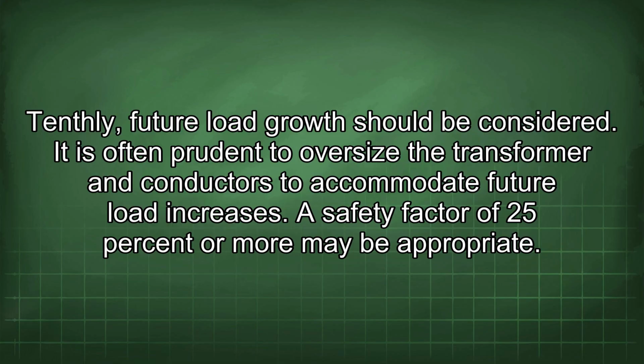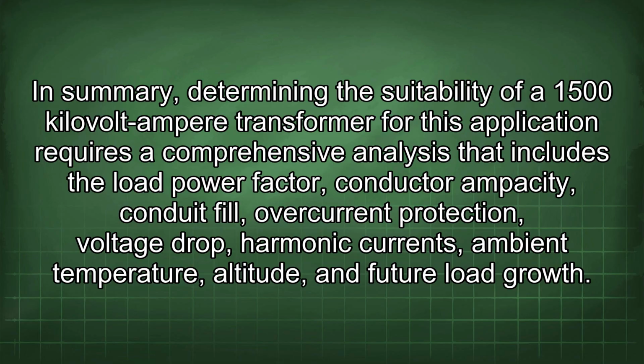Tenthly, future load growth should be considered. It is often prudent to oversize the transformer and conductors to accommodate future load increases. A safety factor of 25% or more may be appropriate. In summary, determining the suitability of a 1500 kilovolt-ampere transformer for this application requires a comprehensive analysis that includes the power factor, conductor ampacity, conduit fill, overcurrent protection, voltage drop, harmonic currents, ambient temperature, altitude, and future load growth.